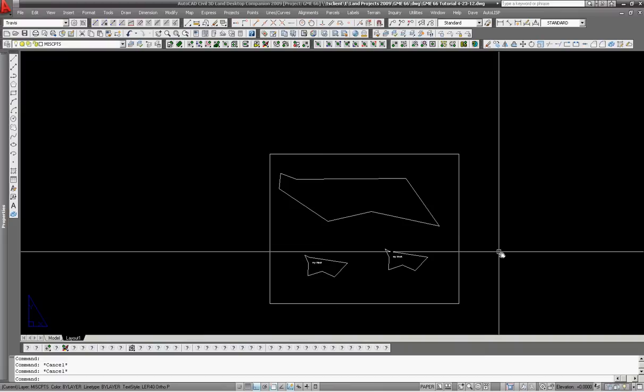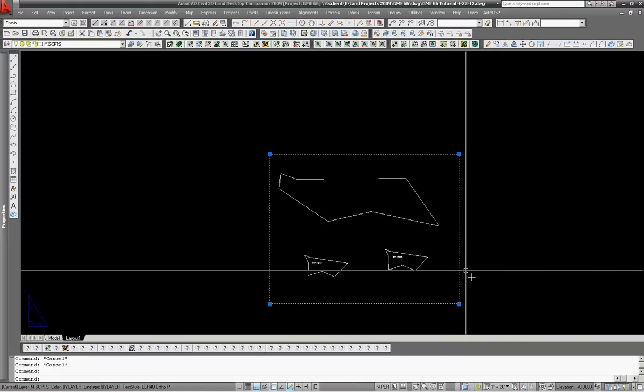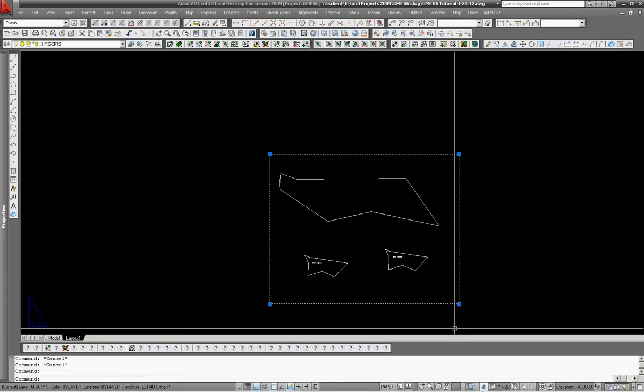In other words, you had it at a 1 to 20 scale. If you zoom in and out, now it's at some weird scale. If you pan around, it's not showing the area you want. So a lot of times what I will do, once I decide that this is actually the viewport I'd like, I'll go down here and I will lock that viewport.